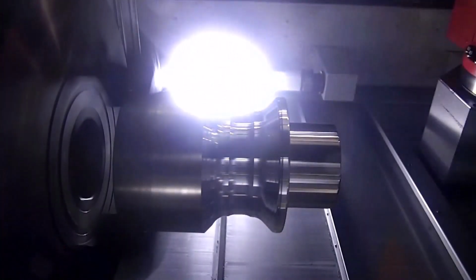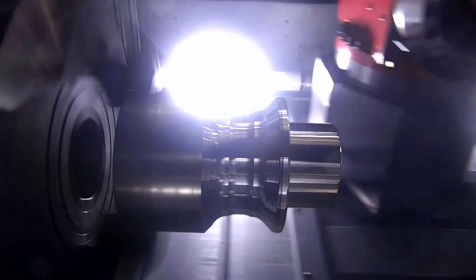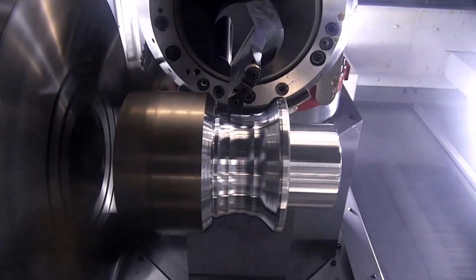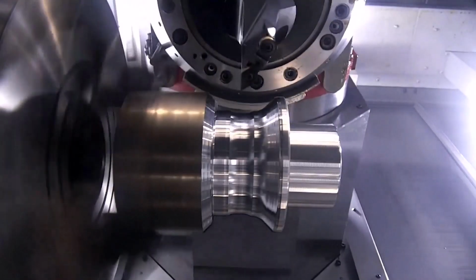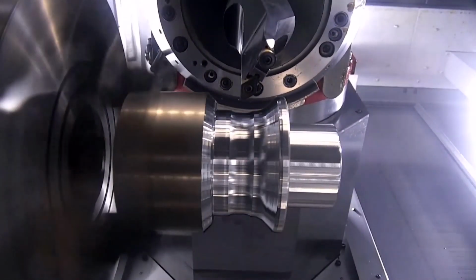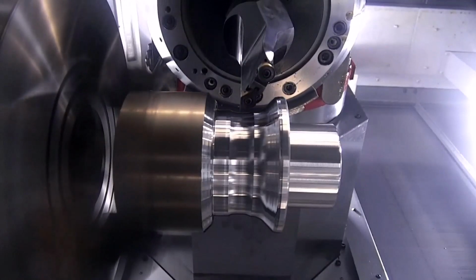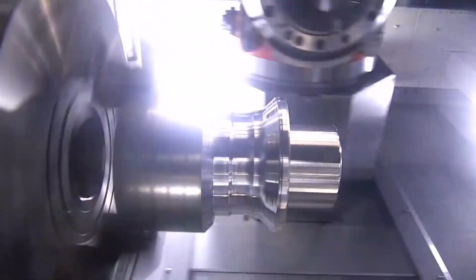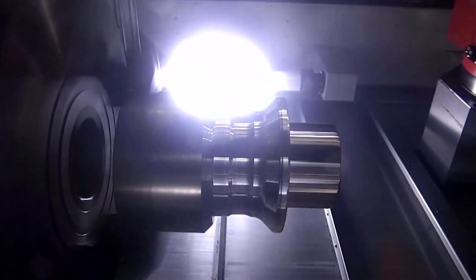And then you touched on something else, Andy, that sometimes the market feels that they can't use a round insert because they don't know how to get chip control. Well, with VoluTurn and the software and the macros that you have in GibbsCAM, it's really no issue. No, you saw it right there. The chip control is fantastic, and when there's a pull coming from the top, it pushes the chips down right into the chip bank. Yes. Yep.